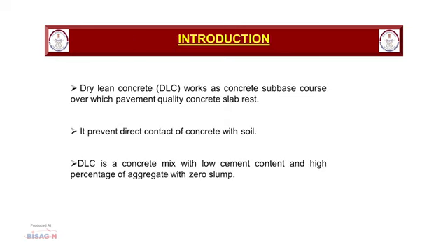operations. Introduction. Dry-lean concrete works as a concrete subbase course over which the pavement quality concrete slab rests. It prevents direct contact of the concrete with the soil. DLC is a concrete mix with low cement content and high percentage of aggregate with zero slump.